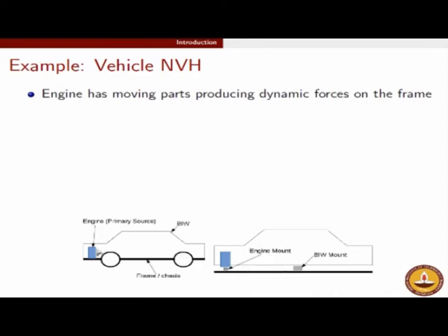And also, you see, despite the vibration of the primary source, that is the engine, being concentrated in a small region, within a compartment where the passenger possibly does not bother to know what is happening, the problem is that this small engine residing in this big car is actually able to cause a global annoyance onto the entire BIW, right? So a local problem has become a global problem now, because everything was getting connected to the frame, right?